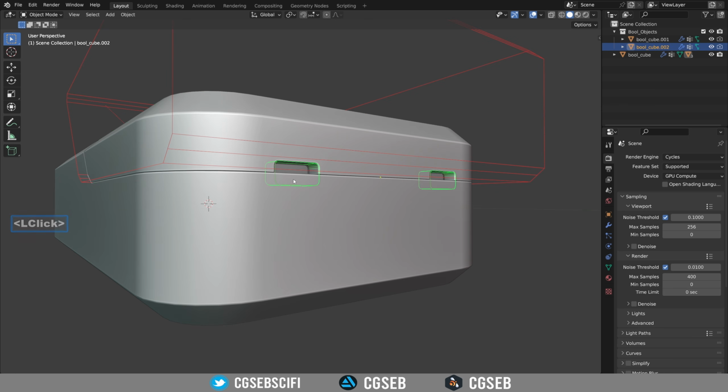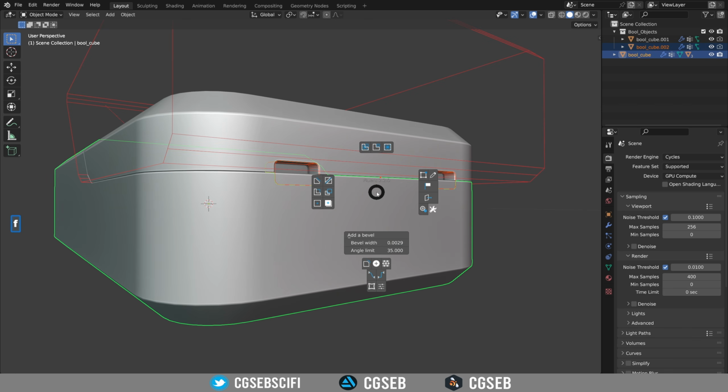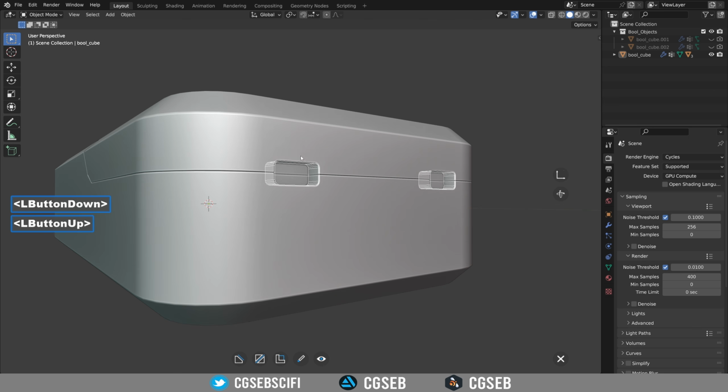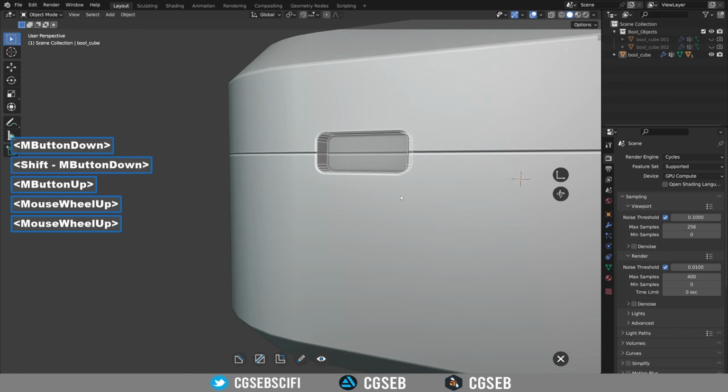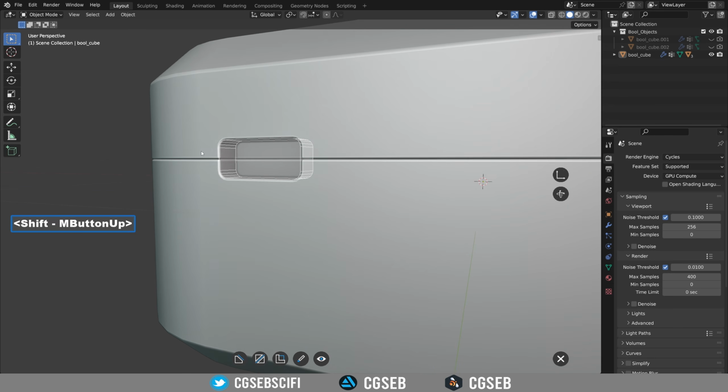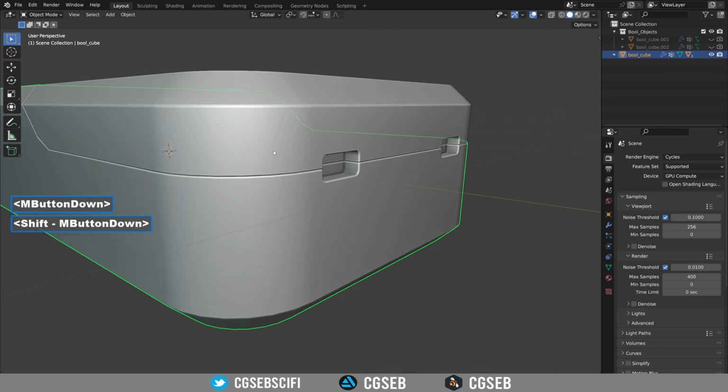Select the cutter we just used and shift click on the bottom part. With the Fluent menu, we are able to use the Boolean tool, and this will create a Boolean operation between the cutter we selected and the object we selected the second time. For this, we will not touch anything and just right click.